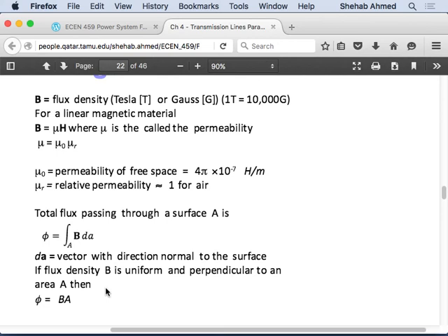So we will calculate H in terms of the conductor dimensions and the material of the conductor. After you calculate H, you will assume a linear relationship between B and H, which is defined by the permeability of the material, right? This conductor is in air, so our relative permeability will be 1. If the conductor is underground, the relative permeability will be different, and you will be given a relative permeability.